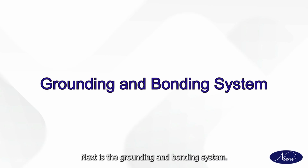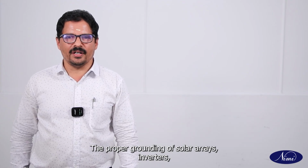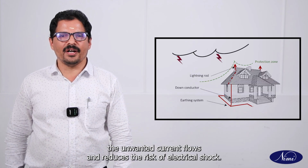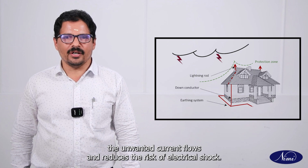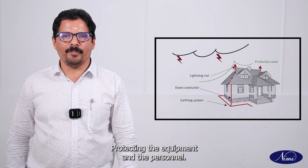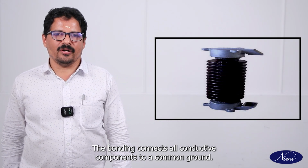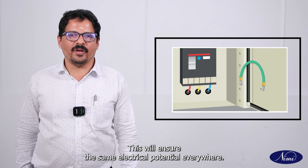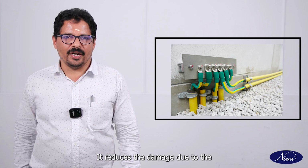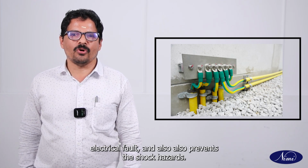Next is the grounding and bonding system. Proper grounding of solar arrays, inverters, transformers and other electrical equipment prevents unwanted current flows and reduces the risk of electrical shock, protecting the equipment and the personnel. Bonding connects all conducting components to a common ground. This will ensure the same electrical potential everywhere. It reduces the damage due to electrical faults and also prevents shock hazards.